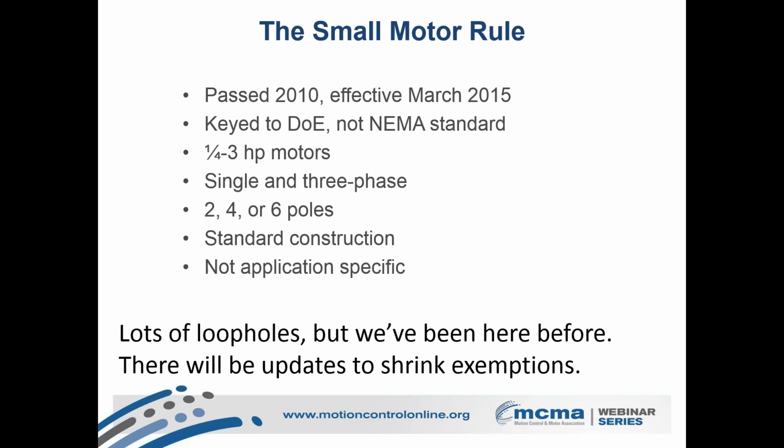And they apply to 1/4 to 3 horsepower motors. That's kind of where they got started with the names: fractional because that's a fraction, integral because the other ones were whole numbers. But fractional doesn't apply anymore because over time, developing the standard, they extended it from just 1 and smaller out to 3. There are a whole number of specifics, but in particular, it applies to single and 3-phase motors, 2, 4, 6 poles,